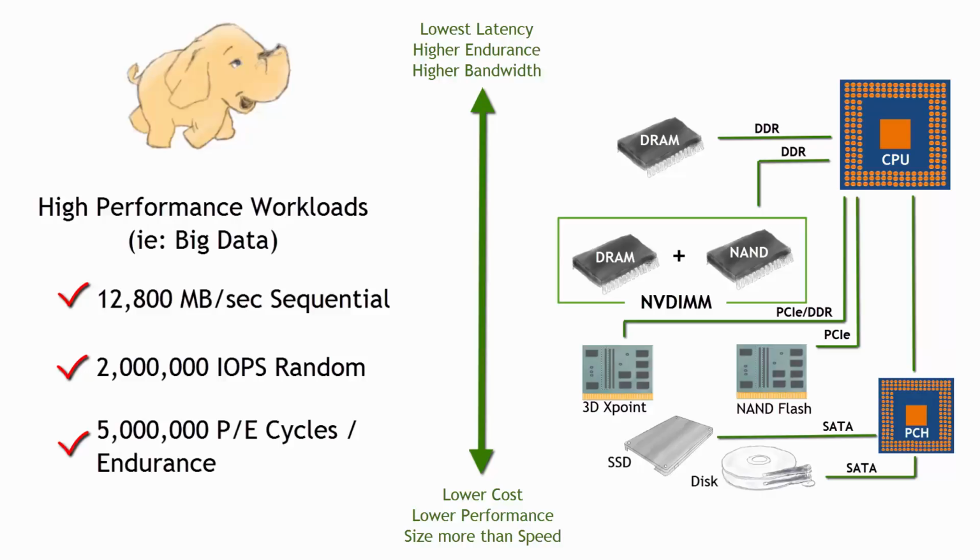Essentially, we're doing our reads and writes and taking advantage of that higher performance and higher endurance on our DRAM, and we have a battery system or some sort of power system so that if, for example, we lose power, it immediately dumps DRAM right into NAND, which will then protect that data within seconds.